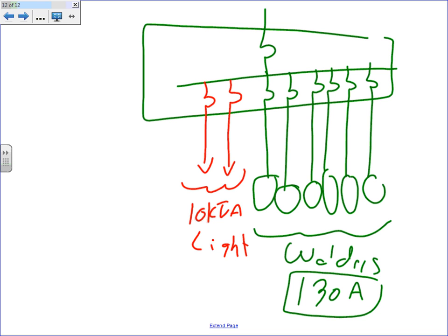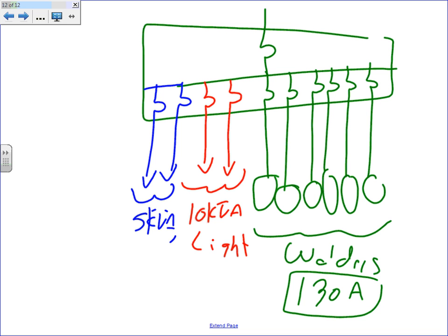Then, to add insult to injury, I added receptacles, another, let's say, 5 kVA. It's already demanded. I applied the first 10,000, which is anyway, there's no 10,000 here, so everything here is demanded. I don't need to multiply by 1.25 because that chunk is already multiplied by 1.25. Everything is demanded, just to make it easier.